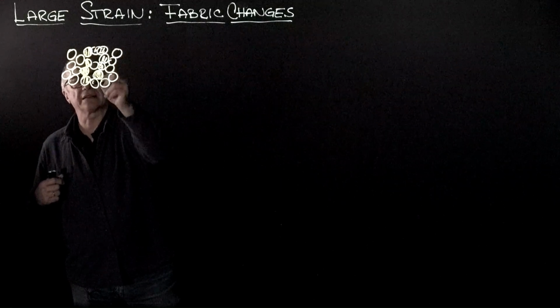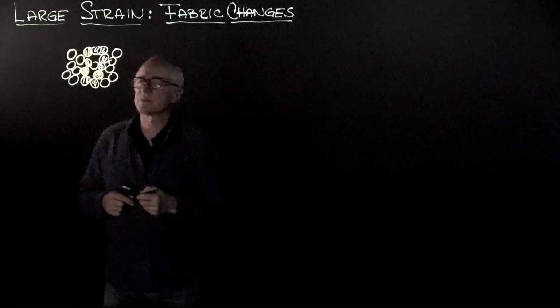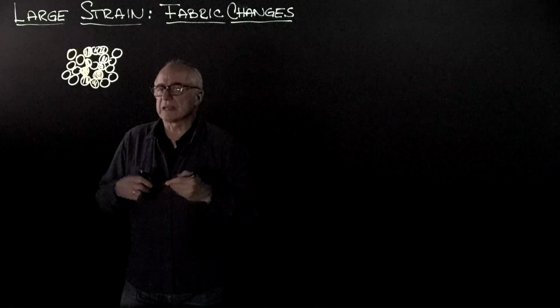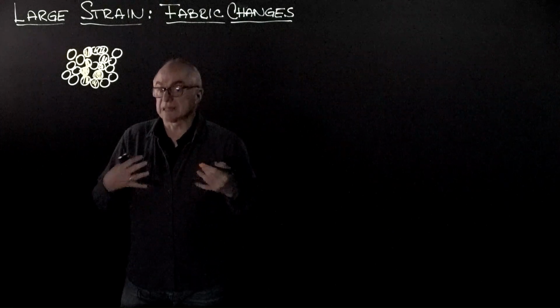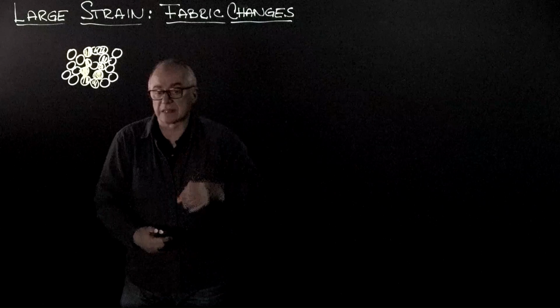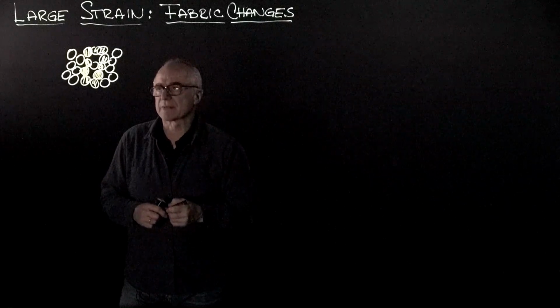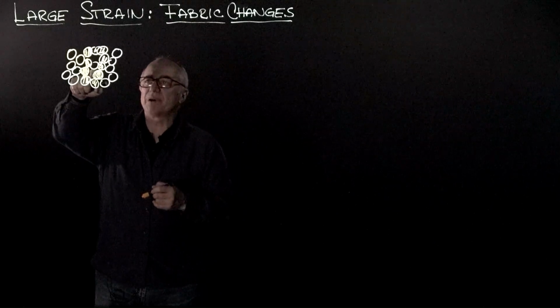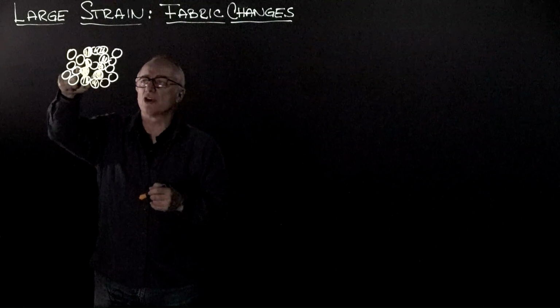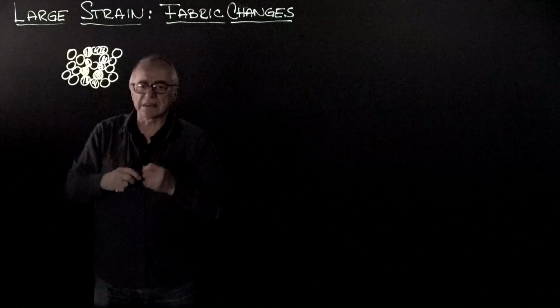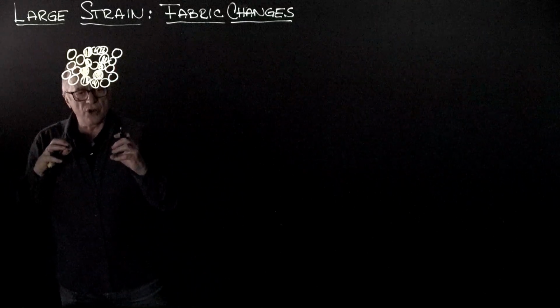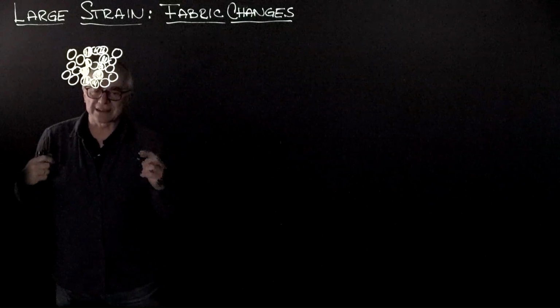And these are called particle chains. And these particles are not only carrying most of the load, but they do it in the direction of the external principal stress. Now, what is interesting is that the particles that are holding those chains and are preventing them from buckling are actually carrying a small load, primarily in the transverse direction.